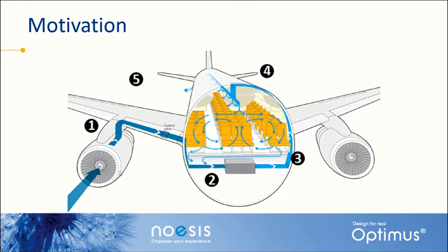That air is combined with recirculated air here at number 2, and this represents the recirculation fan that we will discuss today. The air is then pushed through a number of orifices or pipes, I guess, where we will change the diameter of those pipes, and then the air is let out, of course, through the gaspers that we showed before. That air is then sucked by the recirculation fan back into the system.